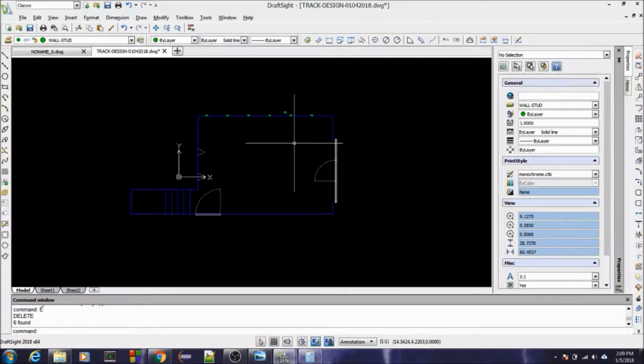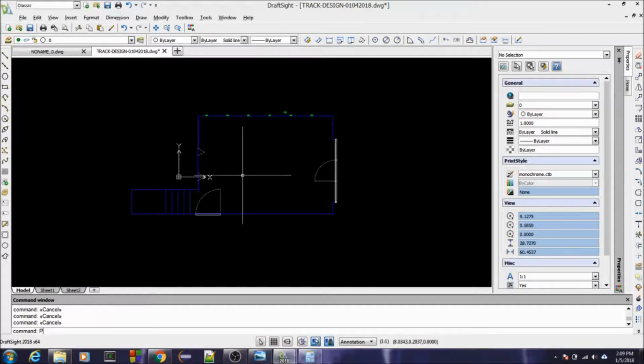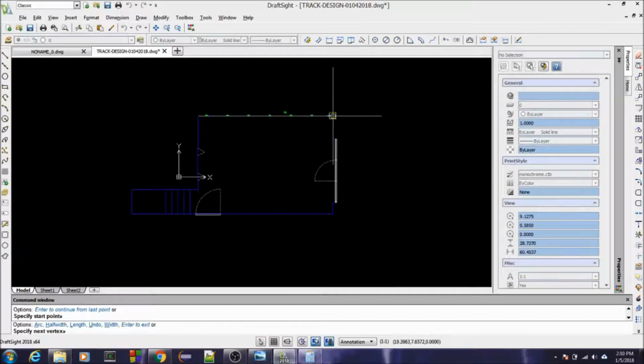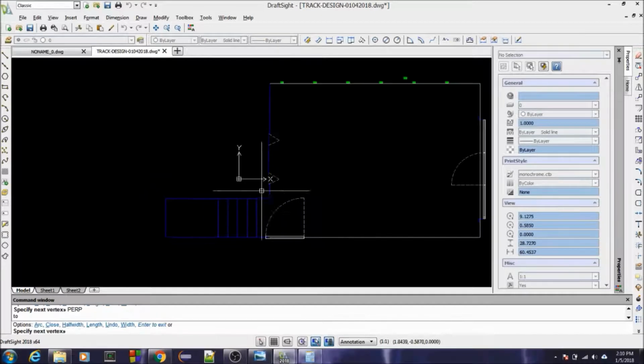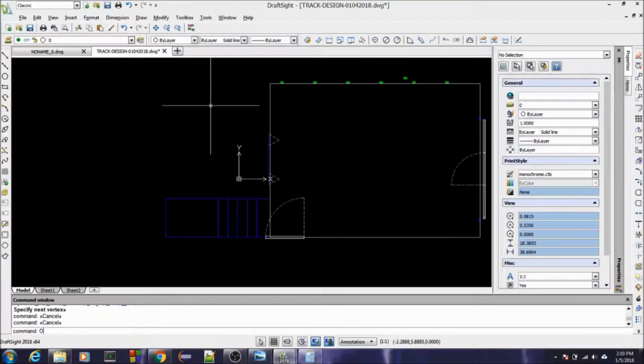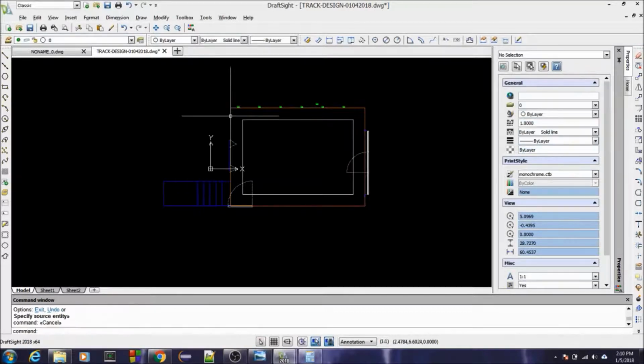So guys, I hope this was helpful. Before I get out of here, put it back on layer 0. So let's just say you guys are doing a shelf layout similar to me. Say your shelf is going to stick off the wall 18 inches, which is going to be 1.5. So I'm going to offset that box I just drew 1.5. So that's where the edge of your shelf would be.